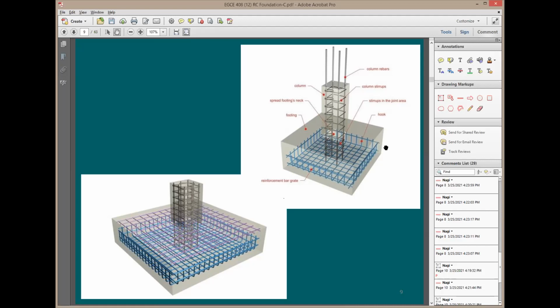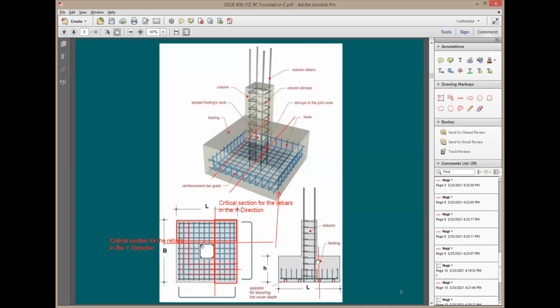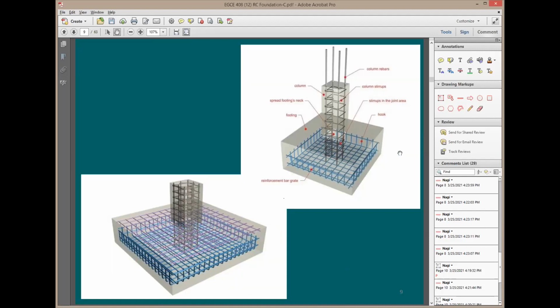You're going to have a few rebars running in both directions. It's not going to be that many, but generally speaking, just for construction purposes. And also, you need them for the minimum steel ratio, because this minimum steel ratio is to reduce the amount of cracks, shrinkage cracks, in the concrete. So you don't want to leave all the top area of the footing empty of any rebars. You'd like to put some rebars in both directions.